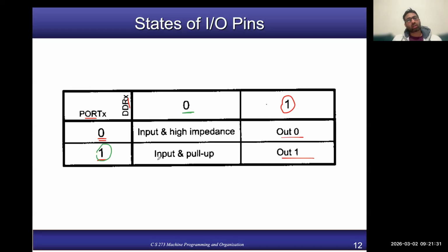But if you connect the input pin externally to nothing, still you will get logic 1 by default, right? However, in the case where you have configured the port as input mode, but you have not enabled the internal pull-up resistors, and you have not connected the pin externally with any signal, then it will be high impedance. High impedance means that there will be random noise, so your signal will not be stable.